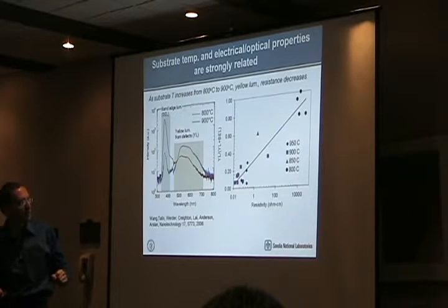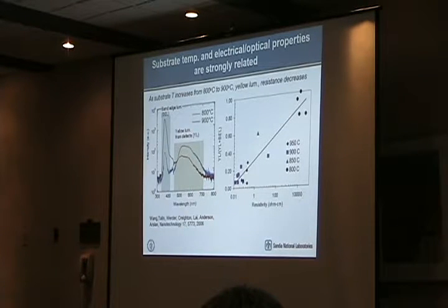And the conductivity becomes much higher, as opposed to nanowires grown at lower temperature, which have very high yellow luminescence and are very resistive. So what we think is happening is that carbon, because that's the big difference between our growth, we use MOCVD, and people that don't use MOCVD, they don't use a carbon precursor, carbon gets incorporated. Carbon has been associated or linked or theorized to be linked with a deep acceptor. And so what it does is simply compensates the intrinsic N-type nanowires, and that's why they're so resistive. Okay?